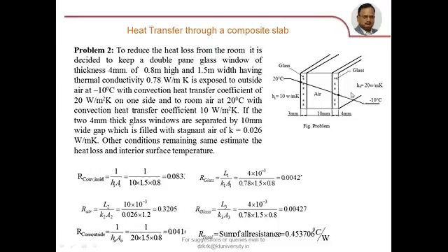But if you closely observe, the convective heat transfer coefficients inside the room and outside are given. Which indicates that in addition to the conduction resistances of these three materials, the surrounding medium also offers some amount of resistance for heat transfer.